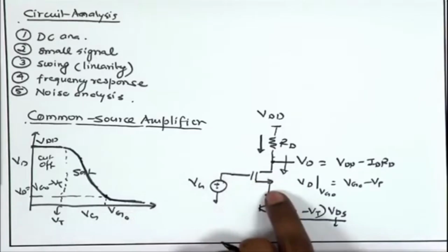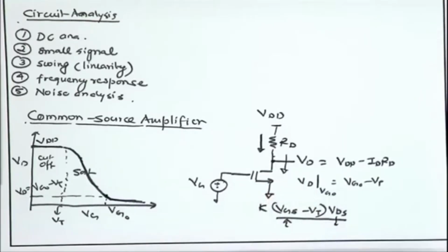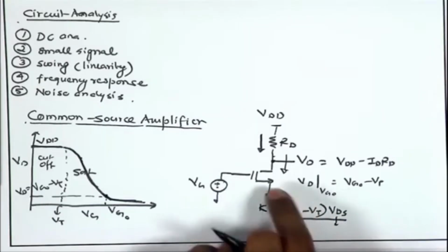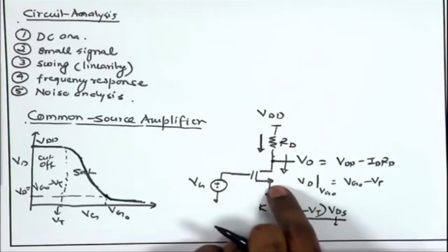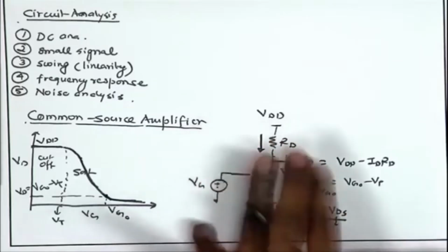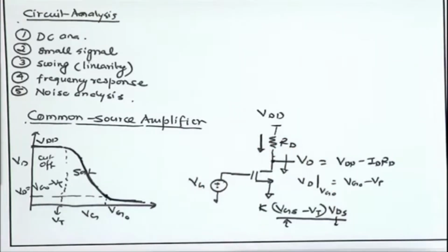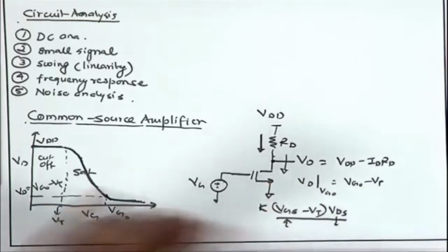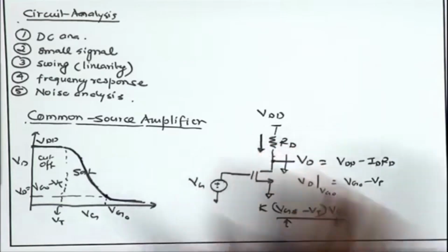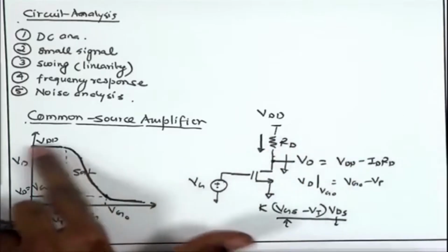So, definitely this is probably the first integrated circuit inverter, or digital inverter, that people had used before the implementation or invention of CMOS technology, because at that time the only transistor available was NMOS, and this was one of the ways of implementing the inverter rather than MOSFET. Of course, those days it used to be BJT, but this was the first inverter.